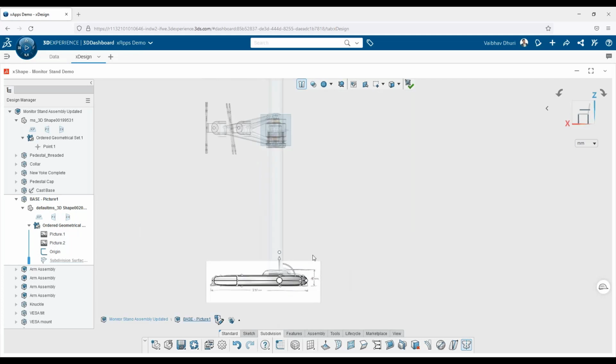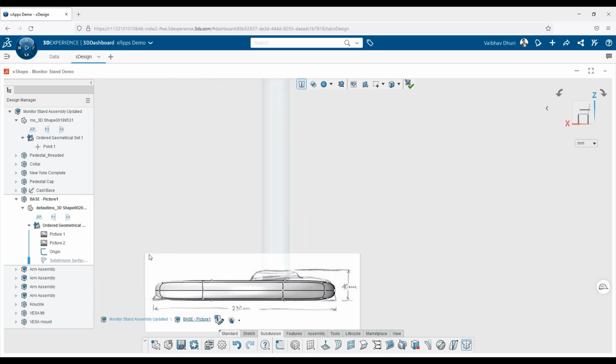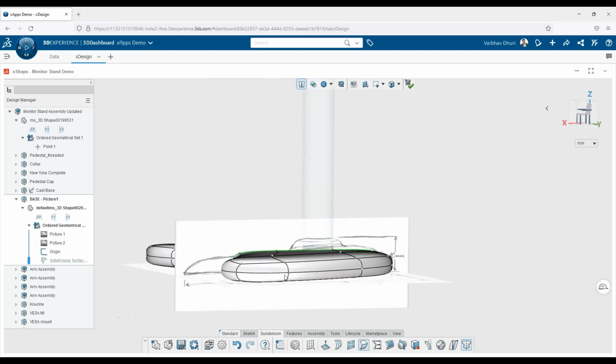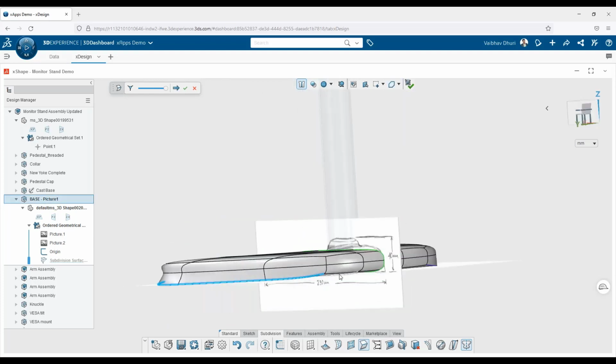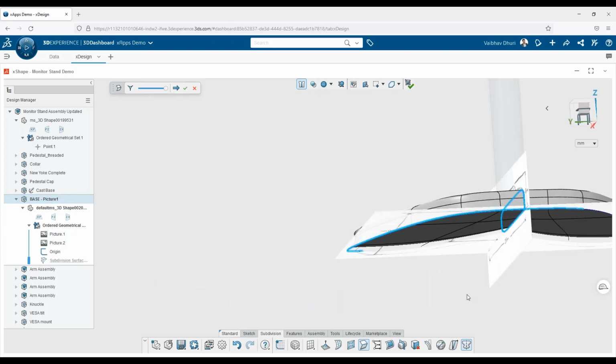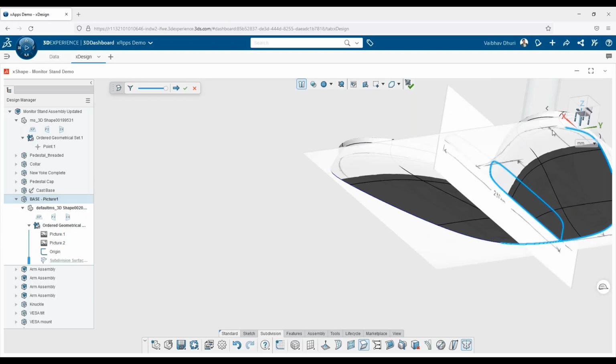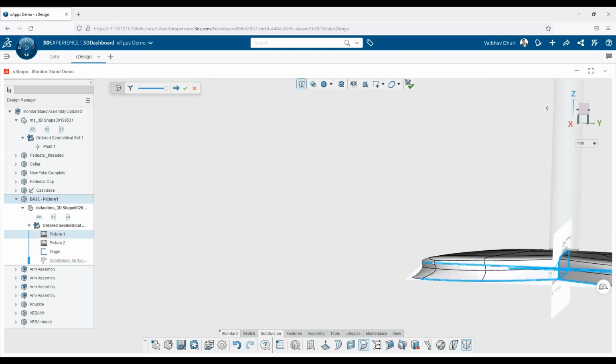Then going to the front view, for example, if I want to flatten a particular section here, that I can do. So here let's say I want sharp edges. I can simply go to this particular command, and here I have selections for edge loops. So here I can select these loops directly on the go and flatten this out. You can see we have flattened this. There are these last edges which are remaining. Done.